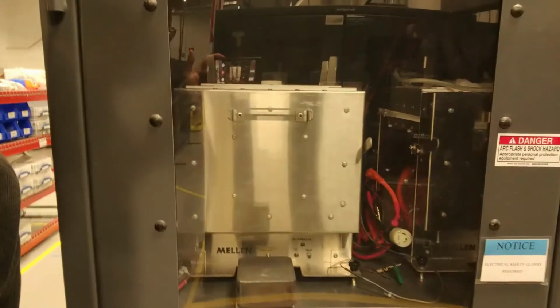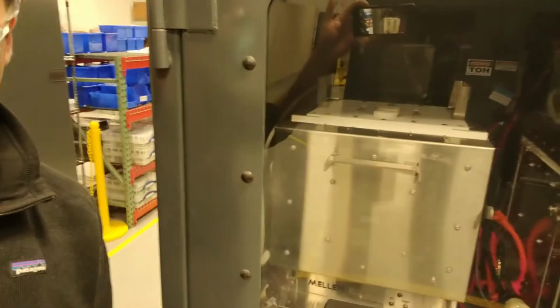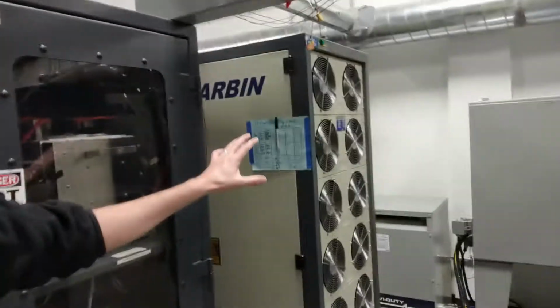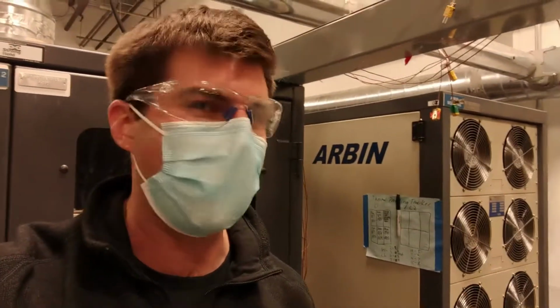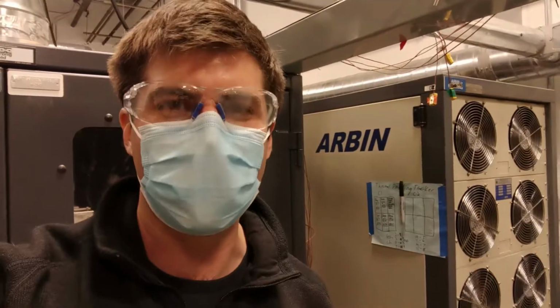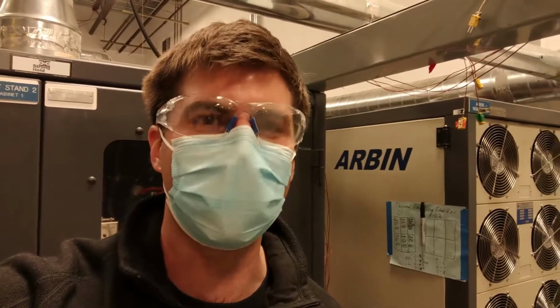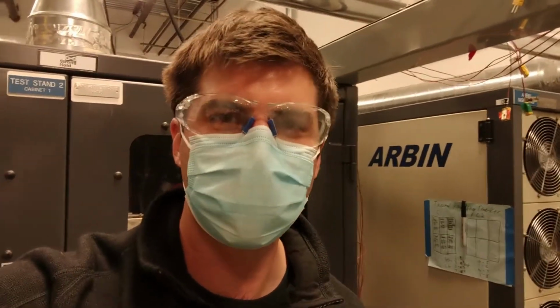But you can see here, these are commercially provided furnaces, and then you see on some of these furnaces on the bottom, you can see some current electrical leads and voltage sense leads coming out of the furnace that are then connected to big battery testers like this Ambri unit here. Again, a commercially available system, which we then use to charge and discharge the batteries, measure efficiency, capacity fade, rate capabilities, things like that. And in a moment I'll show you the test furnaces that we're using for the large capacity cells, which obviously are going to be much larger.